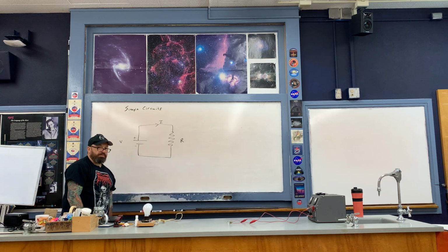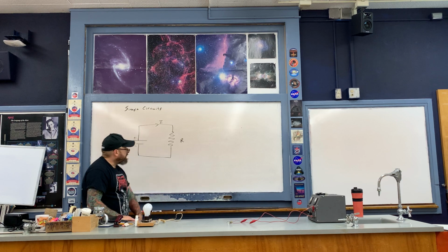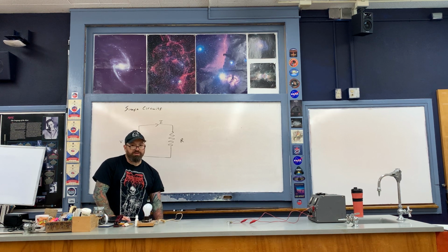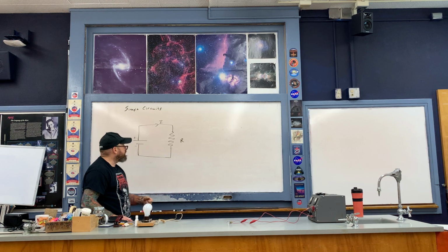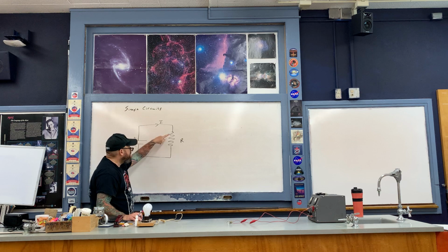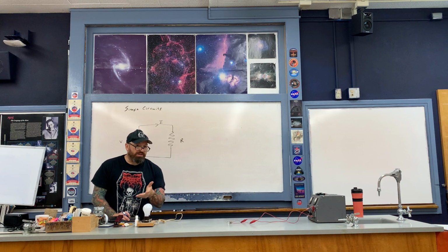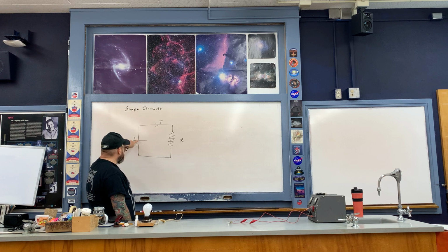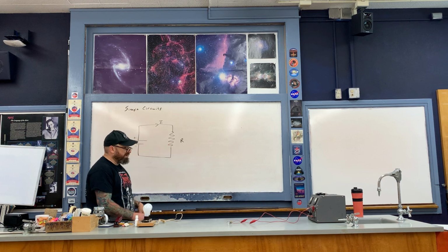Okay, so going back to my simple diagram here, once again, a little bit more in-depth meaning here with regards to the symbols. The resistance, symbol R, once again, is this jagged line right here. This is essentially representing the energy that is being lost as heat. However, notice that some of the other lines that have remained from the earlier portion of my description are still straight lines. Here and here, like so. We always draw straight lines in circuits to represent equipotential surfaces. So this then means that there is no potential difference between here and here because all of this is a straight line. There is no potential difference between here and here because all of this is a straight line.